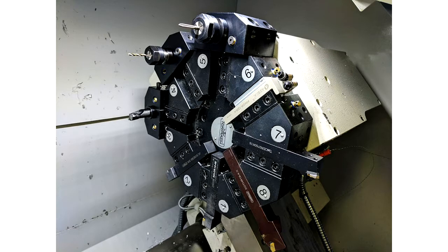This is in a traditional fixed tool lathe. Now there are more advanced lathes that will be covered in the next class, and those are called live tooling, where these tool positions with the rotary tools can actually turn on and spin, and in that way they can do their routines in places where they're not on center line. And so they cut flats or hexes or slots in the cylindrical pieces.